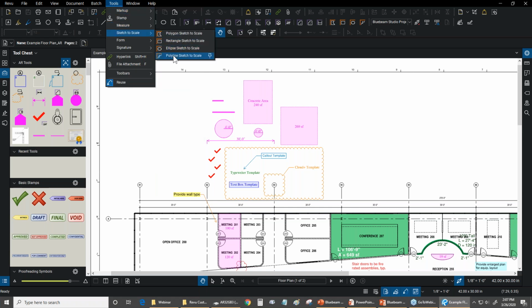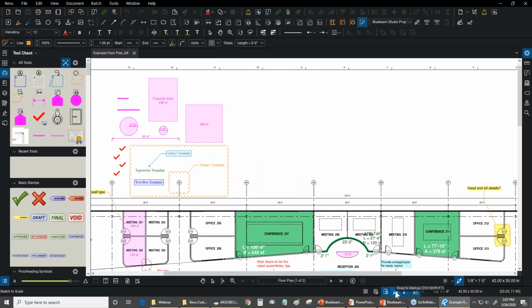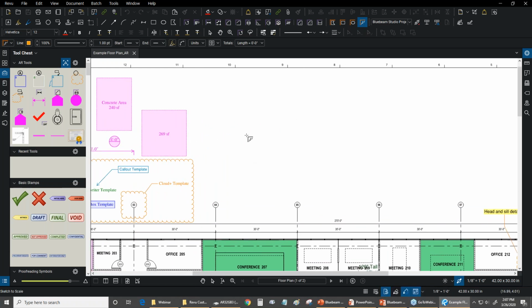So we're going to do the same thing with these. Let's look at the polyline one first. So just like I said, turn off this thing, because all of these little leader lines are quite useful, but they can make things a little bit hard to draw accurately, and we don't want to use them right now. So we're not going to snap to markup. We can still snap to content. Let's make our first origin point.